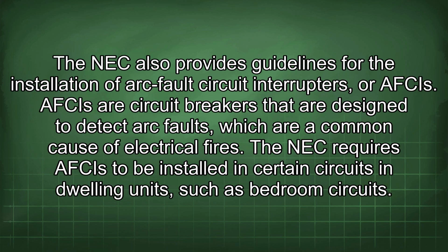The NEC also provides guidelines for the installation of arc fault circuit interrupters, or AFCIs. AFCIs are circuit breakers that are designed to detect arc faults, which are a common cause of electrical fires. The NEC requires AFCIs to be installed in certain circuits in dwelling units, such as bedroom circuits.